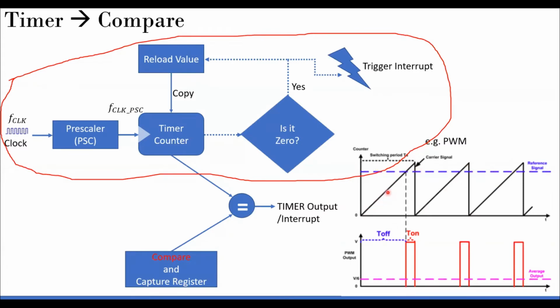So what happens is, till that time, the counter value is always less than the compare value, so nothing will happen. The moment they become equal, an interrupt is triggered, and my interrupt service routine will start something like this. This is the output of the interrupt service routine, which is going to the PWM output. There's no magic here. It was 0 before, so I will toggle that output to 1 or some high value. And then that value will remain high till the next interrupt comes.